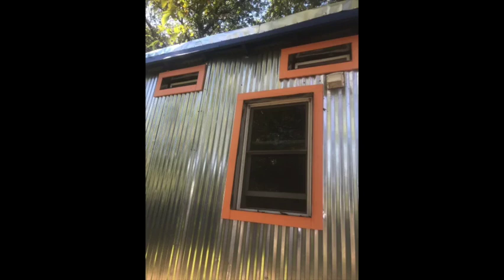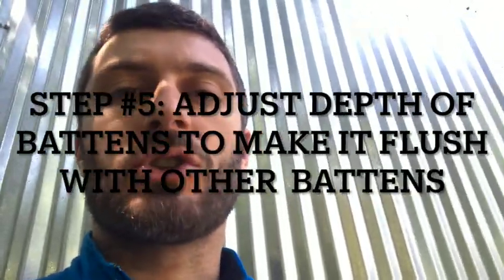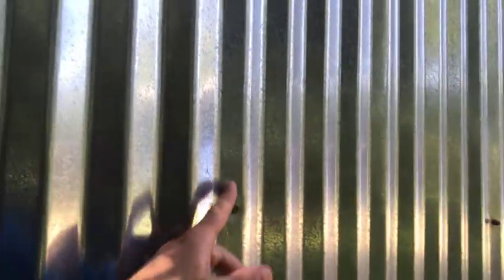You want to make sure when you are installing exterior mineral wool bats that there's no gaps between any of the bats that you install, and the bat itself will just butt up against the L flashing around the windows. Once you install the external insulation for an entire wall, you're going to want to go over each one of the battens that you installed and make sure that they're flat with the other battens. So for example, this would be a batten right here, this right here would be a batten, and then over here, see my hand, this all the way up would be a batten. So you want to make sure these 2 battens are lined up with each other and are flat, so that way when you lay the siding onto the house, it will appear flat and look nice.